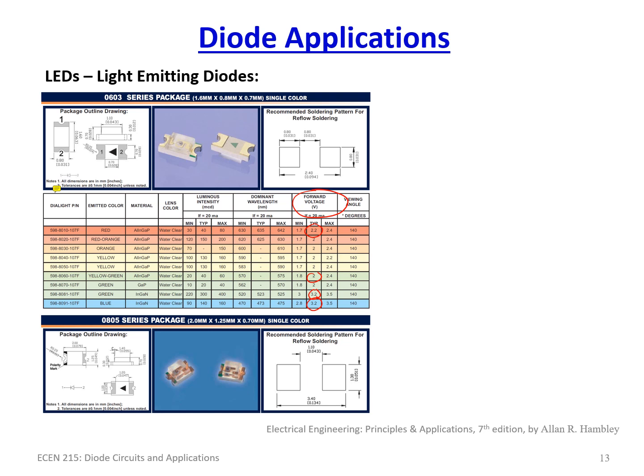The current luminous intensity is what you end up with if you have a current of 20 milliamps, measured in microcandles or millicandles. And of course, this is the dominant wavelength, blue being 470 nanometers, red being 630 nanometers. So you can just see the wavelength spectrum, what the lens color is, the size of the chip, all that kind of information.